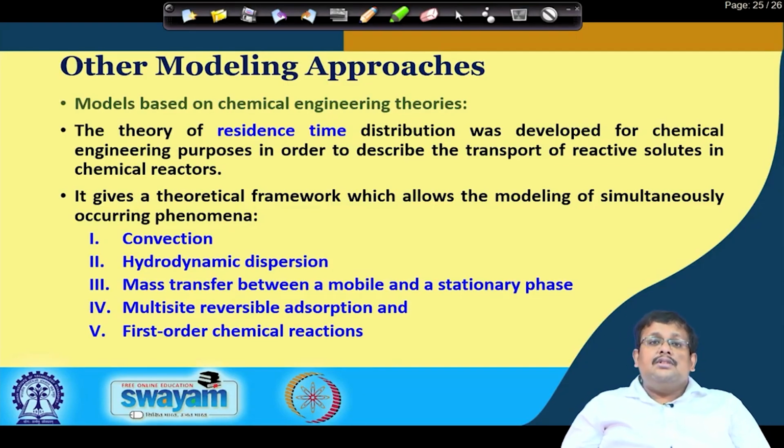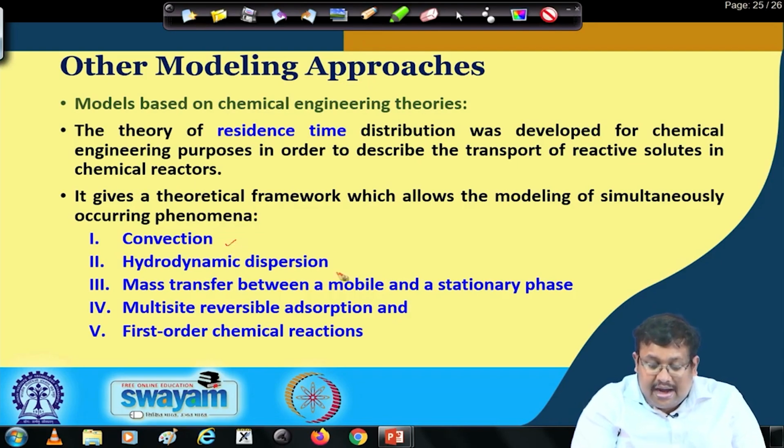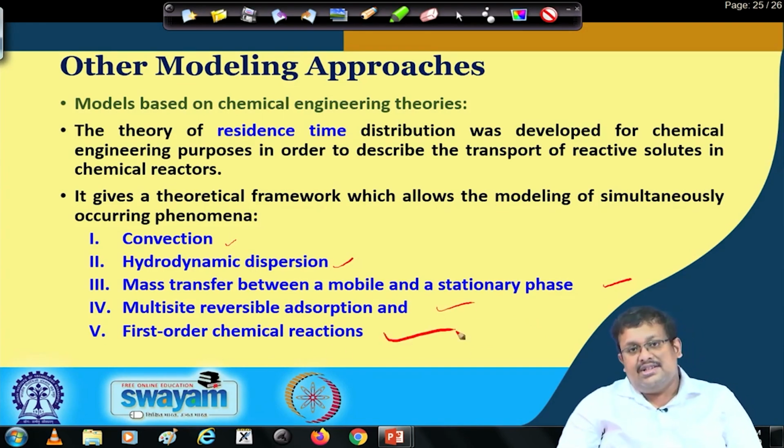Which are those? First of all convection, hydrodynamic dispersion, mass transfer between mobile and stationary phase, multi-site reversible adsorption and first order chemical reactions. We have already discussed the first order chemical reaction and multi-site adsorption.